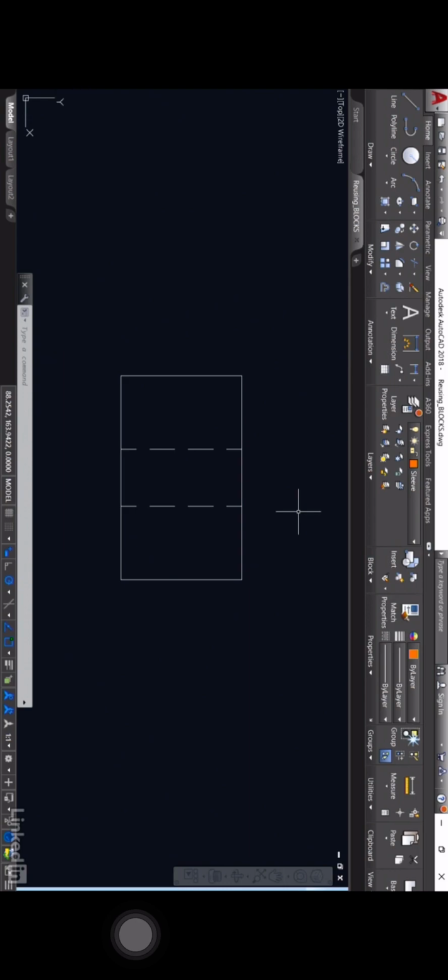We're starting another chapter now in our AutoCAD Certified Professional Prep course. And what we're going to look at is reusing design content. So basically reusing data that we've got in existing drawings to perhaps reuse in the existing drawing or perhaps a new drawing. To do that, we're going to look at using AutoCAD blocks and AutoCAD external reference files or XREFs.